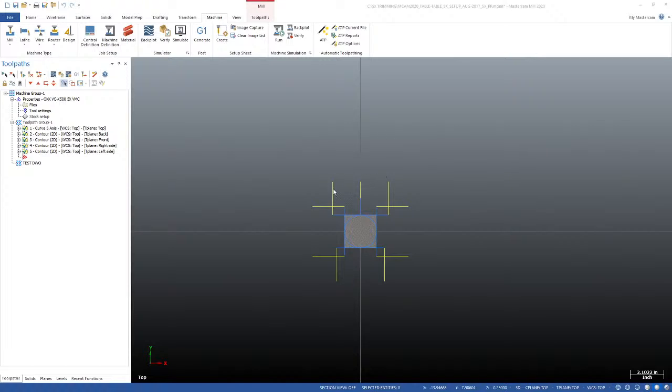Now this is another great example of where we want to use position to change the location here. So I'm going to go translation in XYZ, and let's go -20, -20, and let's go 15 in Z. We need to go up in Z because we need clearance for our head as we're cutting this part. So now if I go and run simulation, same part, I haven't changed anything about my part.